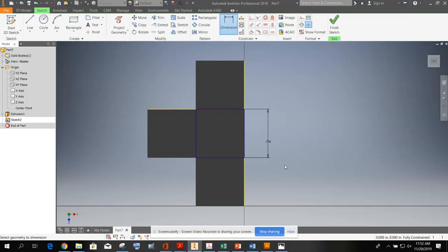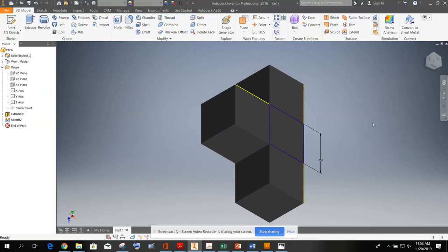Now notice, it's a square. I didn't require that it would be a square. But if I press this button, F8 right here, it'll show me my constraints. So one of the constraints I have right here is this. It's a square on top of a box. Basically, that is telling me that this point right here has to be on this corner. That's the constraint that it added automatically. And there's another one right there. It says that this point right here has to be on this yellow line. And that's why those yellow lines are showing up, because I'm referencing them as constraints. So mine is fully constrained. I'm going to click F9 to turn these off. I don't really need them. And then I finish the sketch.